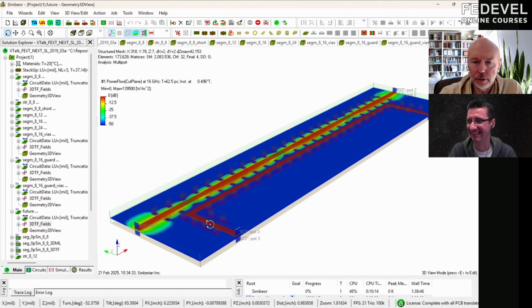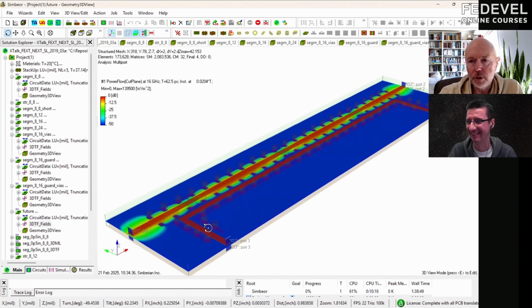Yeah, there is actually a type of waveguide in between substrate integrated waveguide and strip lines, with potential use for 448 gigabit per second, where you intentionally create a substrate integrated waveguide and put a wide coplanar trace inside, and it creates a hybrid of TM10 waveguiding and coplanar mode, which can be used to transmit signals up to 200 or 300 gigahertz without much dispersion.